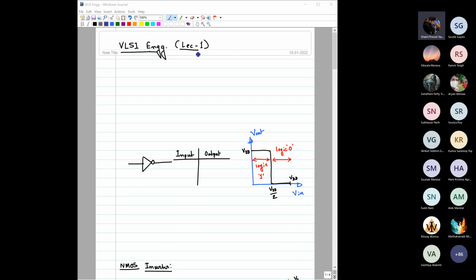If you know how to design the transistor-level MOS inverter, and the significance of its design, then for any NOT gate how you implement it is up to you, but mostly we will consider it in terms of MOSFET, so we call it a MOS inverter. If you know how to design one MOS inverter and the implication of different transistor parameters on the performance of a digital IC, you should also be able to apply the same concept to other gates, for example a more complicated gate, say a 3-input NAND gate.